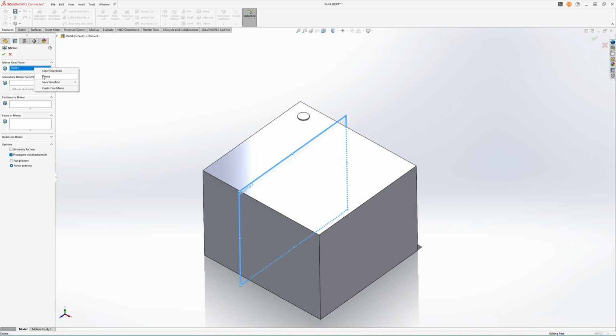Just clear this. Oh, sorry, that's already selected. Click up here. So this, by the way, obviously when you're working over here, you can't see your model tree. Well, you could go back here, but then you can't select the thing you need to select. So SolidWorks pops up the model tree over here. And sometimes due to graphic glitches and stuff, it won't pop up. But if you move your mouse up here, it'll actually activate it and it will come back.